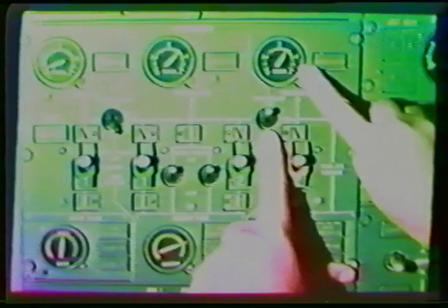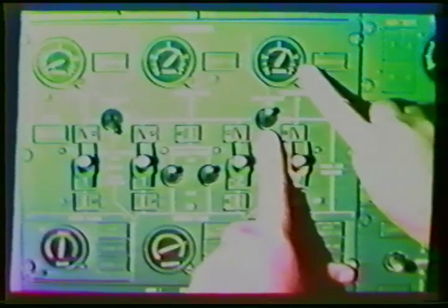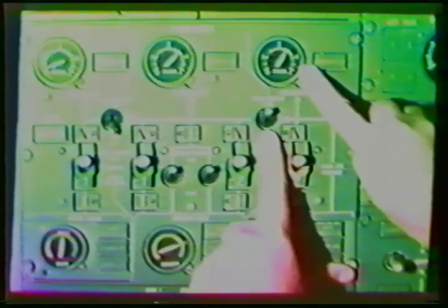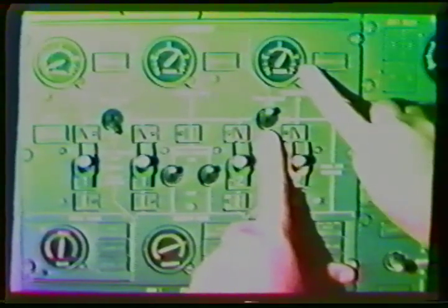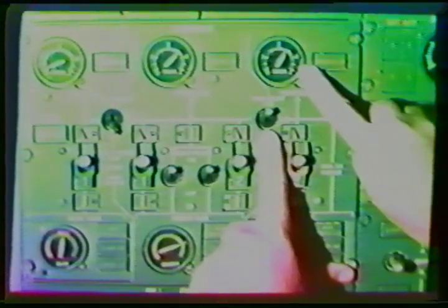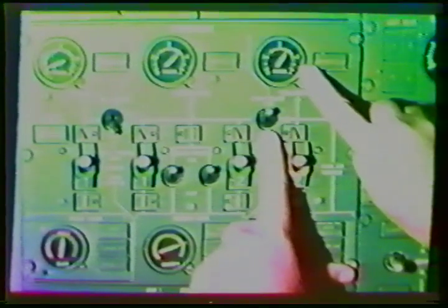An example of hydraulic ground test is shown here. The engines are not running. The green system is being pressurized by its two electric pumps. The right-hand PTU switch is on. Thus, green system pressure is driving the motor pump and pressurizing the yellow system. Note the pressure of about 2,500 psi registered on the yellow system pressure gauge. Because of the low flow rate of the AC electric pumps, only one PTU should be used at a time when the green system is pressurized by the electric pumps.